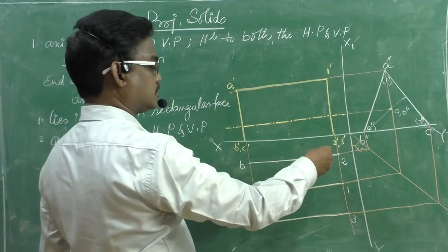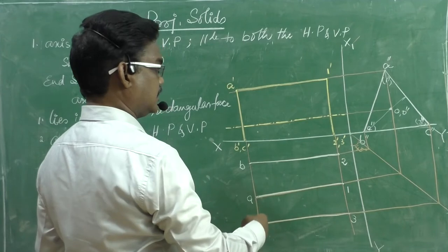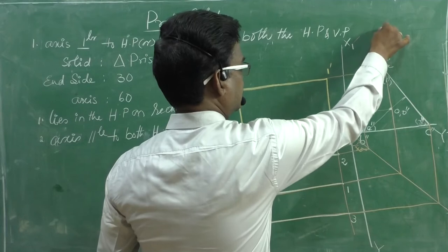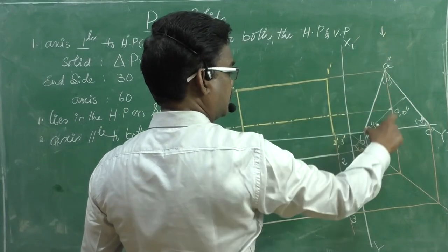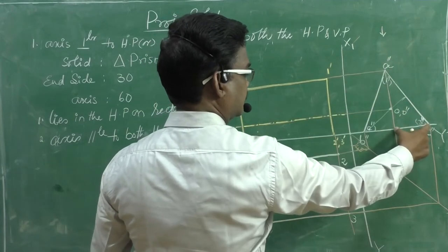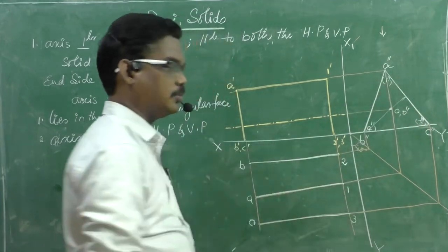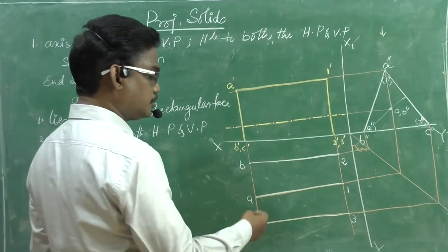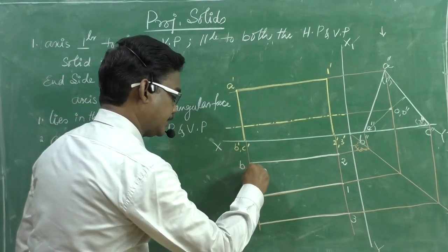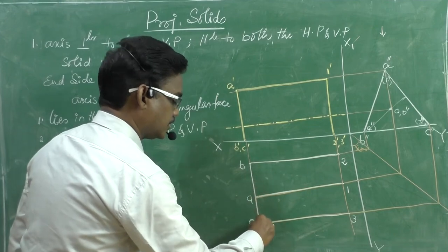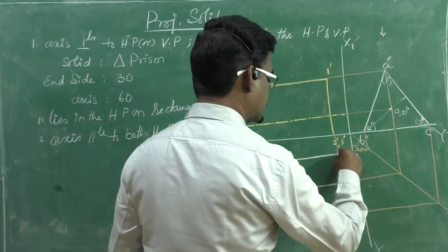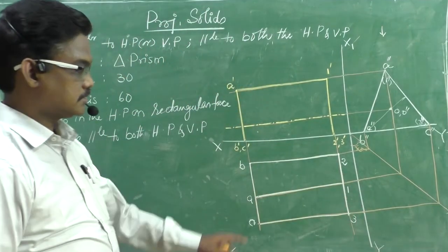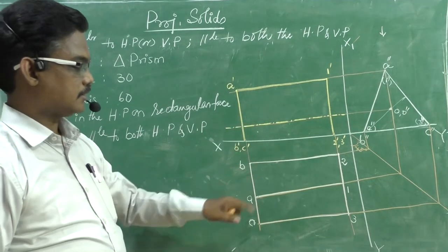And end faces A, B, C, that end face, actually this face is not visible if you see like this, but the projection of AB here and AC here, okay? AB and AC both are visible, okay? Therefore, due to that projection, this end is a continuous line and this end also a continuous line, right? Okay, this is the required front and top views.